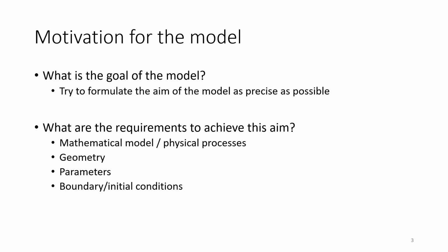Right? So, for example, how heterogeneous is my material? Do I have a good database to design a suitable model? This is very critical, and a lot of models lack those. Right? That's really an issue. Also, the same is true with boundary and initial conditions. Right? Do I have a groundwater well somewhere? Do I have an idea about the aquifer thickness? Do I know if I'm in a confined or unconfined aquifer system? Do I have any idea about the pressure head in the region of interest?